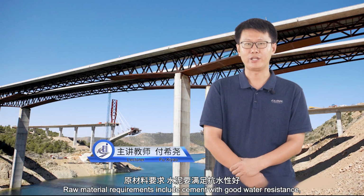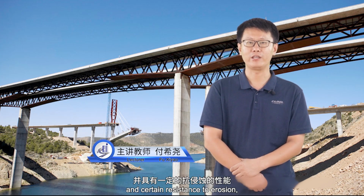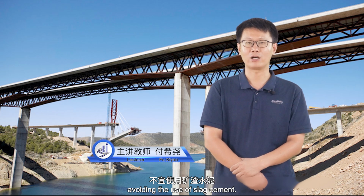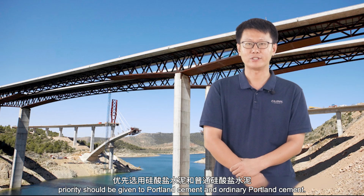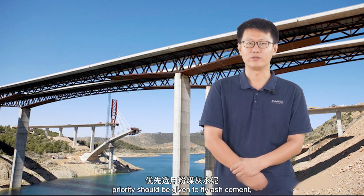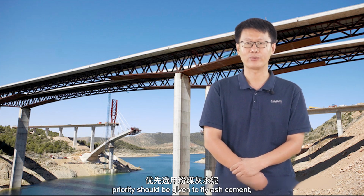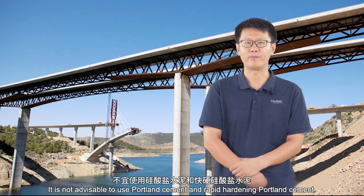Raw material requirements include cement with good water resistance, low bleeding, low heat of hydration, and certain resistance to erosion, avoiding the use of slag cement. When there are requirements for freeze resistance, priority should be given to Portland cement and ordinary Portland cement. For thick and large structure construction, priority should be given to fly ash cement, or ordinary Portland cement can also be used. It is not advisable to use Portland cement and rapid hardening Portland cement.